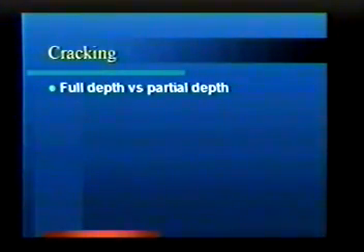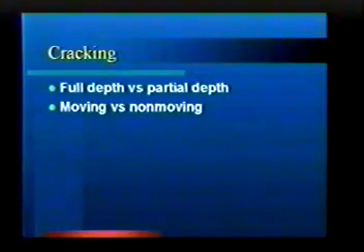Okay, let's get into some cracking. All right, what kind of cracking do we have? Full depth versus partial depth. Big difference. In that slide you saw of the bottom spalling, we had full depth cracking. We allowed the chlorides to get all the way down to the bottom very quickly. If it were partial depth, maybe that wouldn't happen.